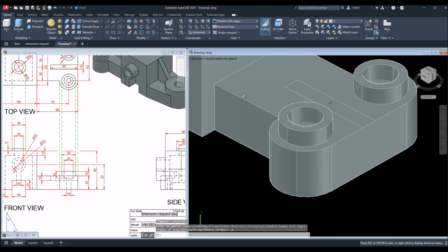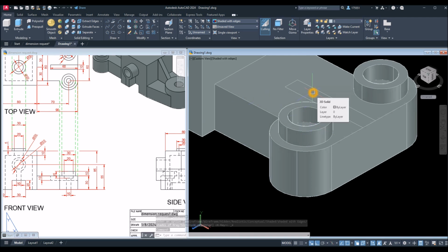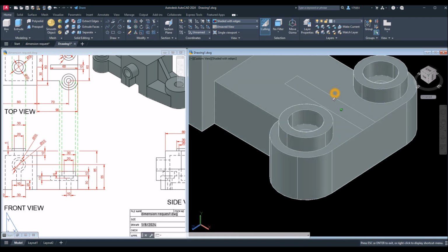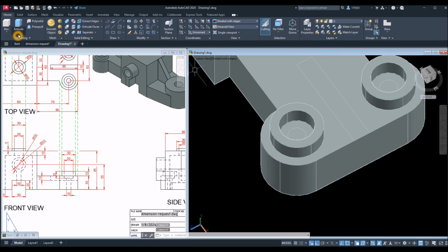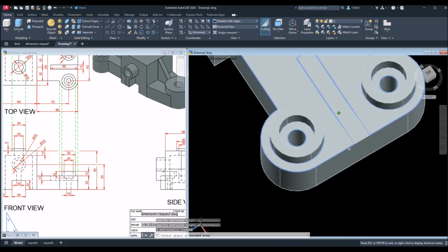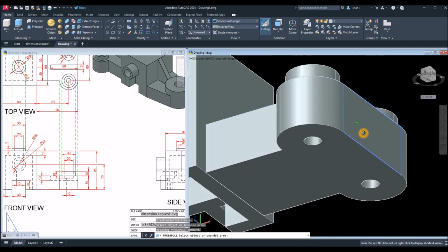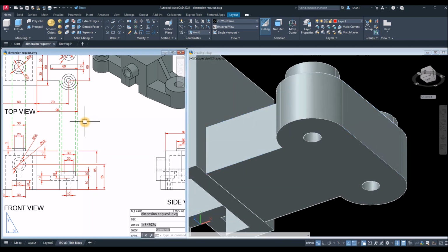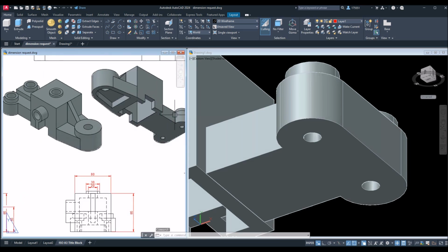and poke a hole. Oh, hold down the shift key and the wheel of your mouse at the same time. Use press pull command, hover over this circle, left click, let go, and left click again. Left click, let go, and left click again. There you go. And I'm just gonna check if there is indentation on this side.